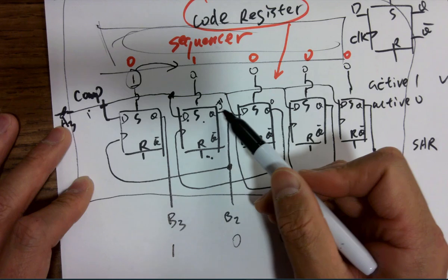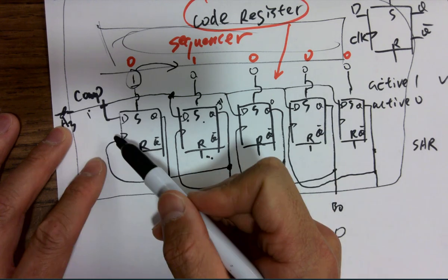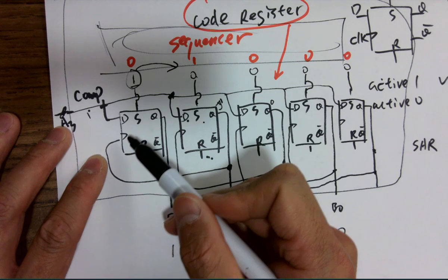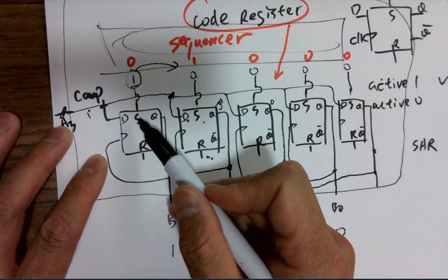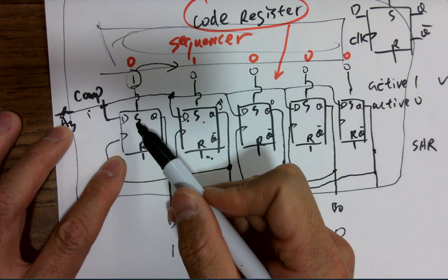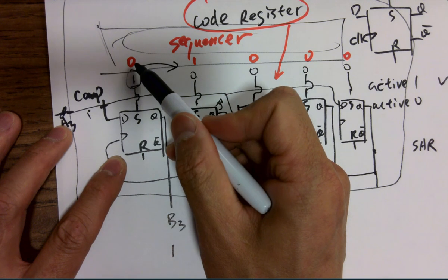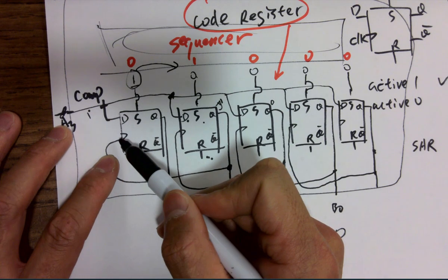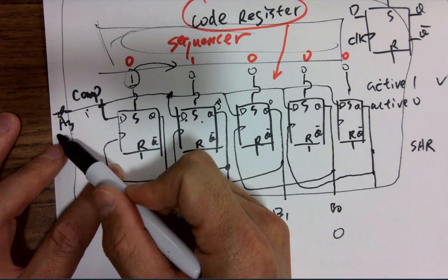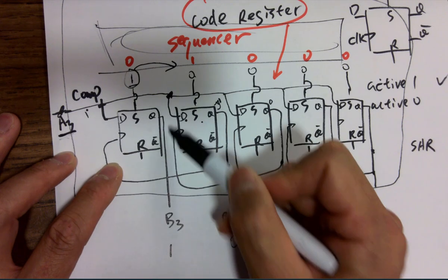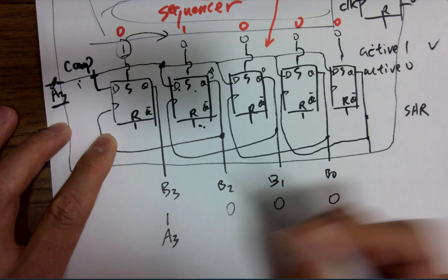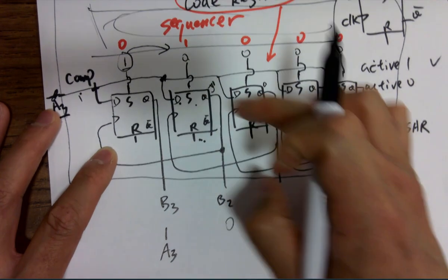And because the Q here is shorted to the clock of the previous stage, that jump, that rising edge, will trigger the clock. It's used as a rising edge of the clock for this guy, and this one becomes what? So first it's the D flip-flop because it's 0 here, right? It's a D flip-flop. It's not being set anymore, and also it's receiving a rising edge. So A3, which appears on this wire, will be registered to here, to Q. Does that make sense? Yeah, we register here.